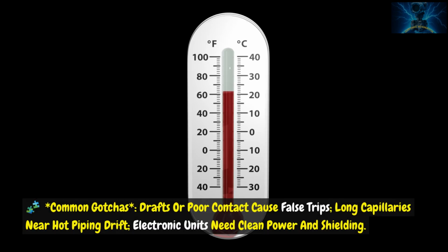Common gotchas. Drafts or poor contact cause false trips. Long capillaries near hot piping drift. Electronic units need clean power and shielding.